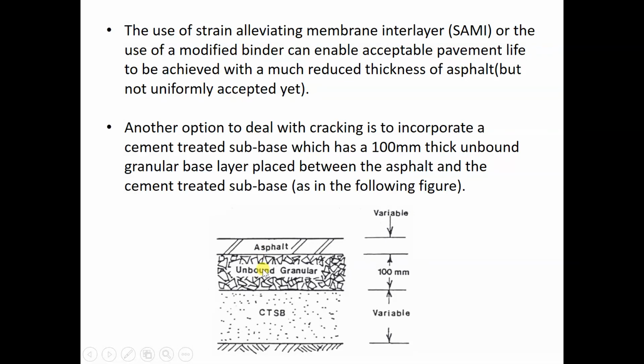But if you put this buffer material, 100 mm of unbound granular material, in between, the crack will be contained and will not reach the asphalt.